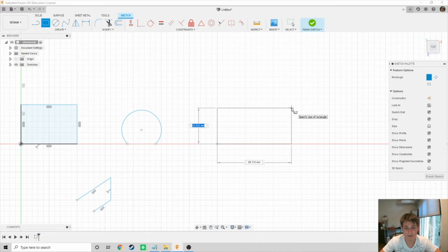Notice that on the left there's a highlighted length of 35 millimeters. This is our dimension. This is our length that allows us to specifically key in our value. So let's say our value wasn't an even number, or an integer. Let's say it was 30.15874. That's not going to be at the intersection of two grids, so it's not going to be a snap. So we'd have to key that in, and we wouldn't be able to get it otherwise.